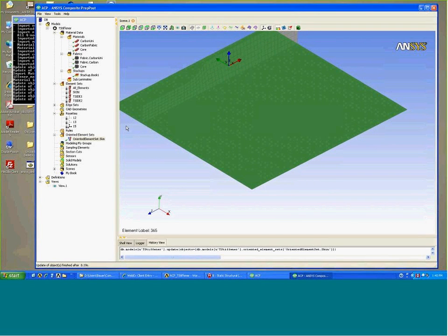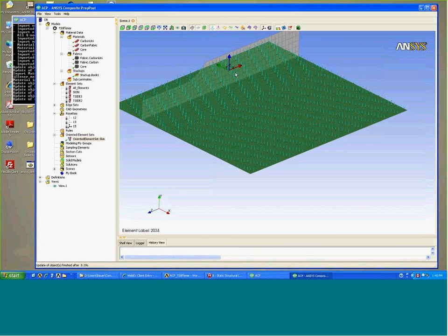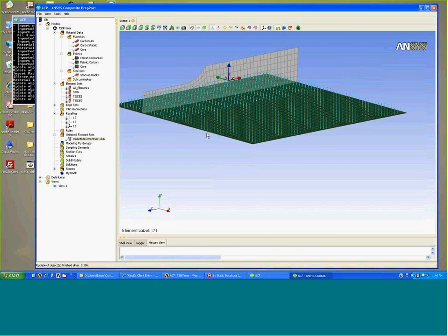A couple of things to check. We're going to assign this to ply definition, so a couple of things to check now are the orientation of the reference system. We highlight our blue icon here. The blue icon shows the basic shell element normal definition. This is coming in from the shell connectivity.